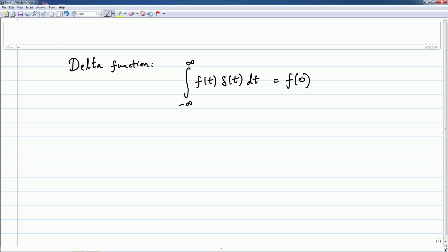There are many dangerous definitions you will see in the text, and it is good intuitively to think of the delta function in various different ways, but if you want to be rigorous about it, it's very hard to define. So a good strategy is to be aware that the delta function can lead you into the wrong path very easily, but nevertheless it's a very powerful thing to use, and in electrical engineering particularly we use it quite often in a formal way. Most of our formulas work with the delta function treated more or less in a normal way. So, just be aware of it.